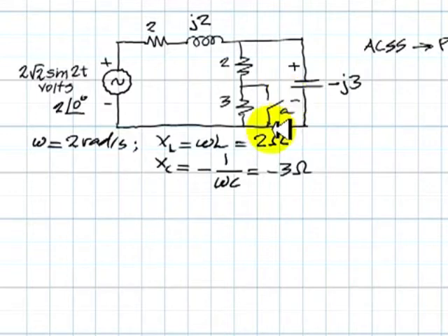greater than 0? Well, what happens at t equals 0? At t equals 0, this switch closes. Or when it closes, it bypasses this resistor. It effectively removes that from the circuit.